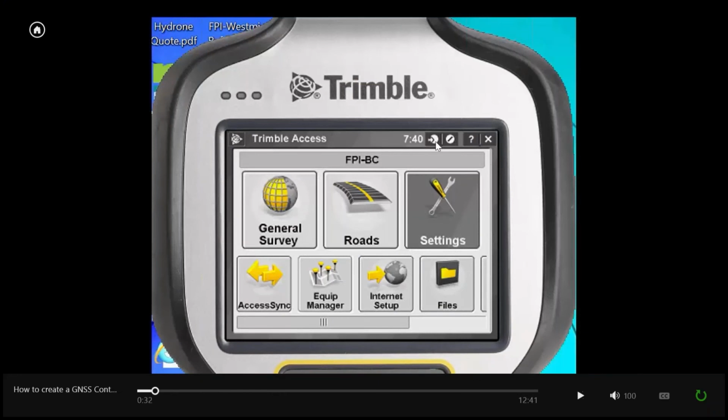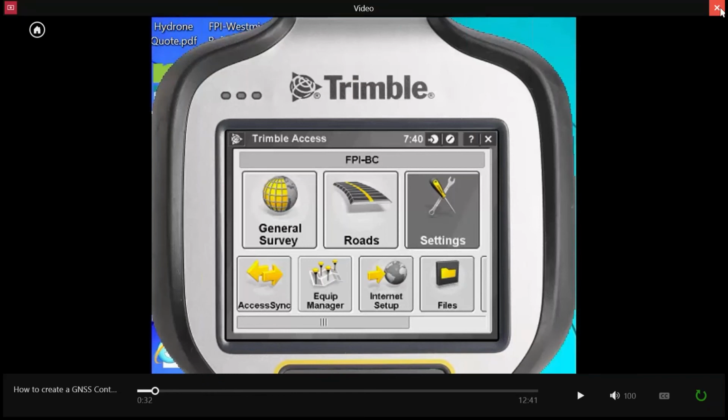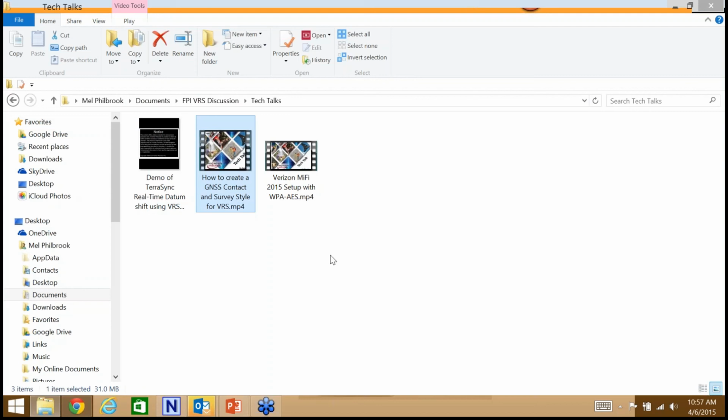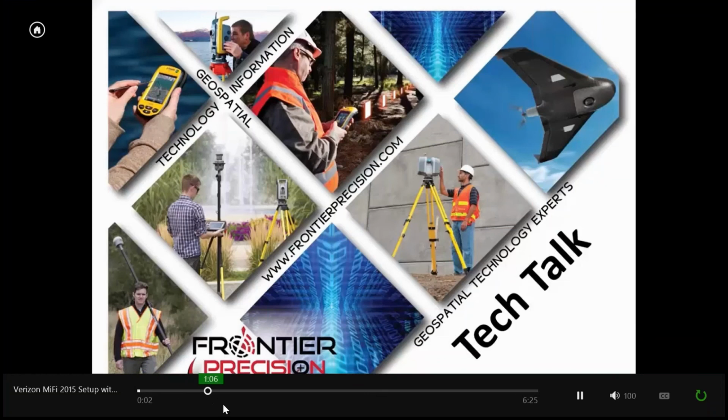If you tap on that icon, there is a base data age, and you want to pay attention to that, especially in areas where you're not going to have as great a cellular connection as you normally would. That base data age should be around the 1 to 2 second range. If it's much higher than that, like 5 seconds or 10 seconds, then you have some poor data service, and if you lose fix, it's going to affect your precision, and you may be required to stay in your position a little bit longer.